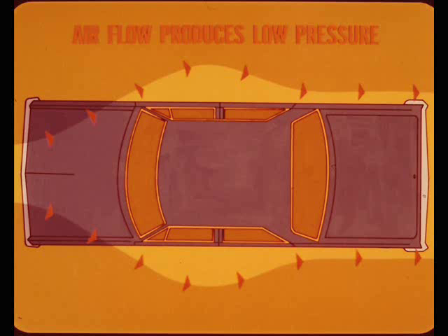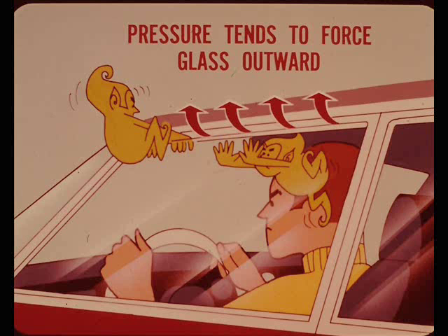With low pressure on the outside, the effect of inside pressure buildup is even greater. That's why, in hardtop models at high speeds, the difference between inside and outside pressure tends to force the top edge of the door glass outward. If the glass loses contact with the weather strip, the air that leaks out can cause a disturbing noise.